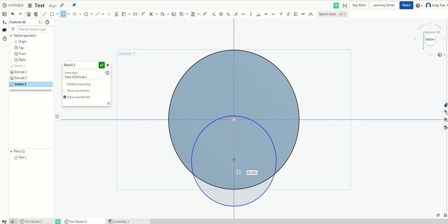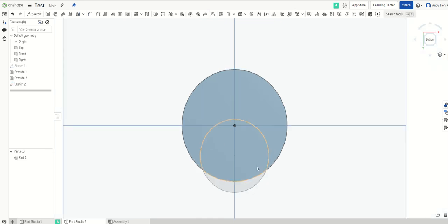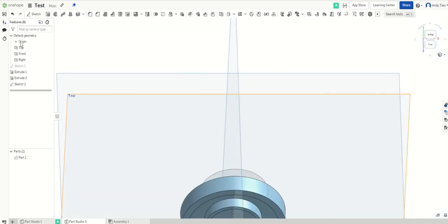So you know, this is center defined, so all I really have to do is just define this radius. I'm gonna just make it 3 and define the length. I'm gonna make it 1.25, and that looks about right, so we're fine. Once again, you want to extrude.